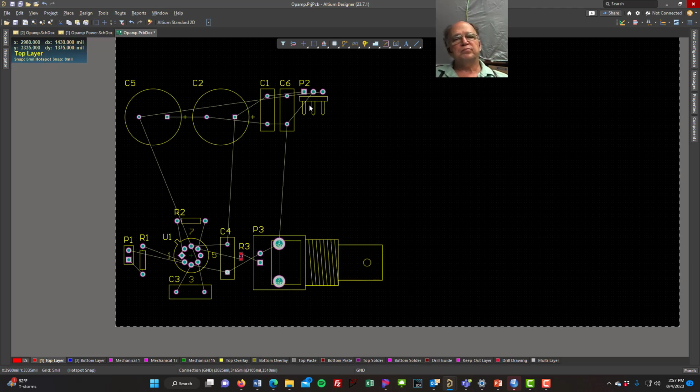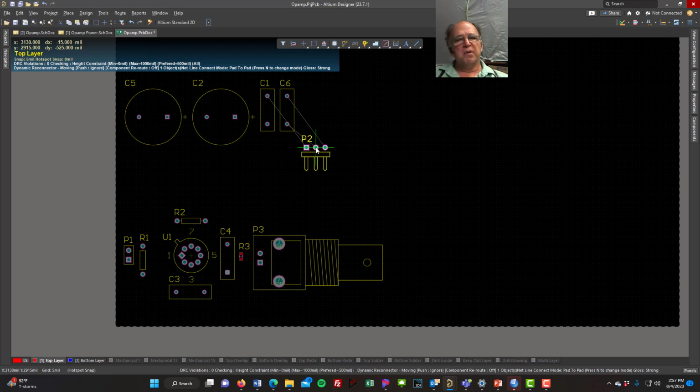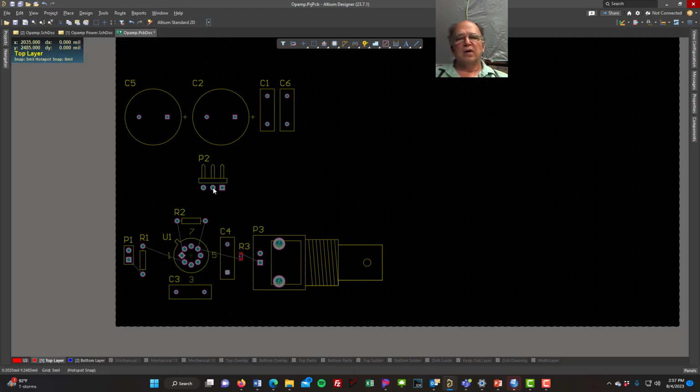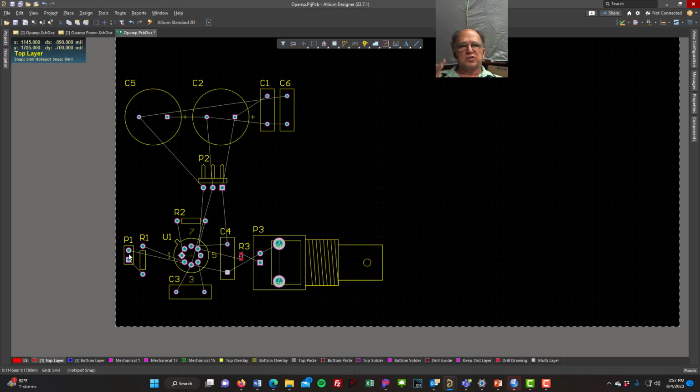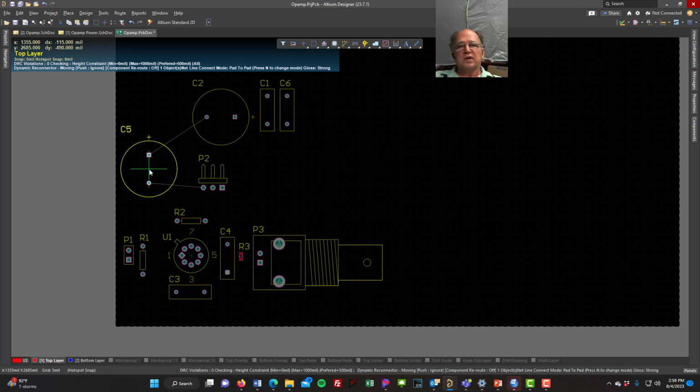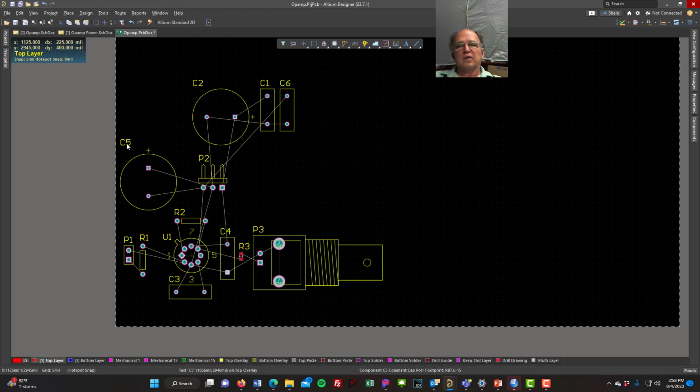No problem. Now, if you remember, when we placed the parts, I placed the 2-pin part as just a vertical 2-pin header, but I placed the 3-pin part as horizontal. See how it's drawn on there with our top overlay? The pins come up and bend over. That way I can take a connector and push it on from the side. And the schematic parts look the same, the footprint's different, so I had an option. Let me take my parts here and place these guys.